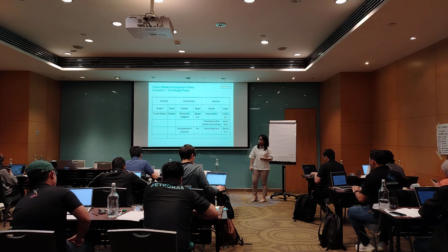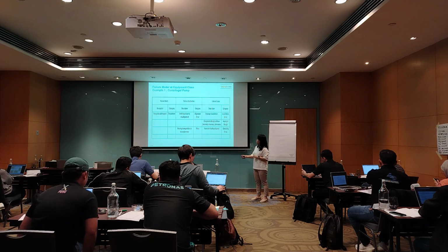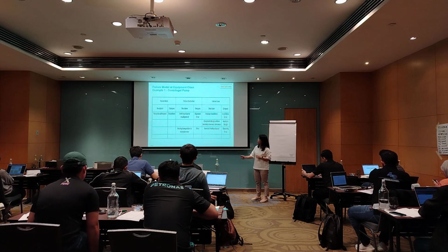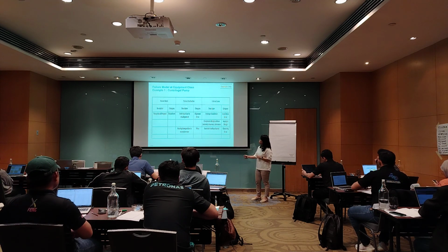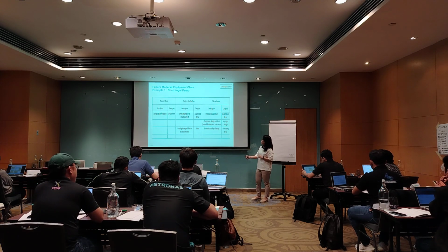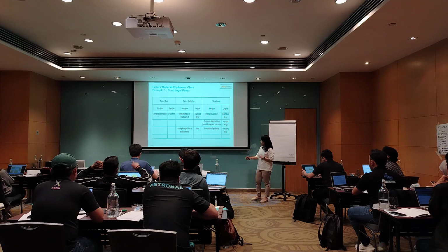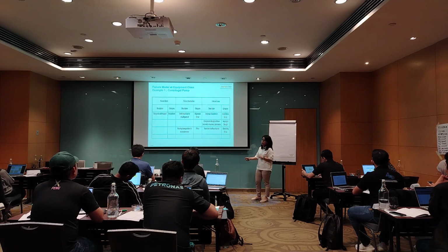Okay, examples. Centrifugal pump seizes, somebody actually gave the example, right? Pump seizes, then the mechanism is that it's stuck due to misalignment. Why is it stuck? Improper installation, or component design problem. Second example, the pump seizes because of many reasons as well.